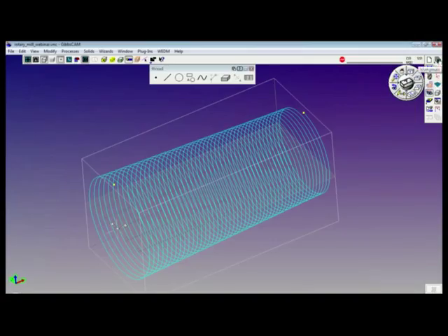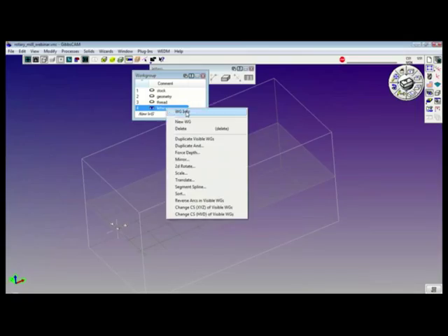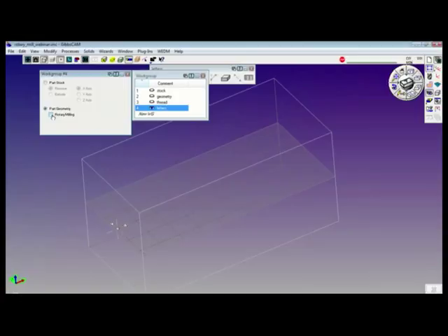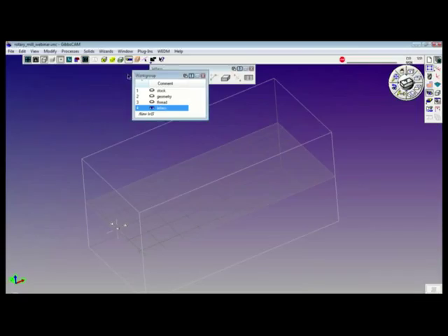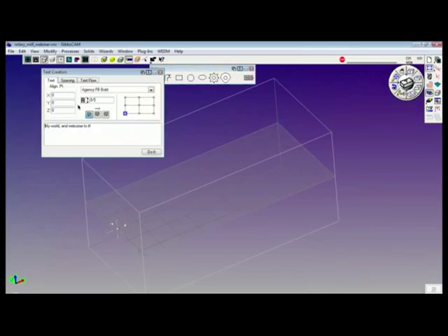So what I'm going to do is build a new work group, and I'm going to call this letters. Okay, right mouse click, work group info, rotary milling. All right, pretty straightforward. Shapes, engraving. Engraving takes a moment to load the font directory. My alignment point will be X3, the center of the part, Y0, Z 1.5.